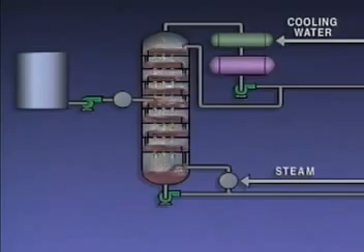Although all distillation towers serve the same basic function, they don't all have the same internal components. One type of tower uses trays called sieve trays to separate vapors and liquid. That type of tower is covered in the tower operation part of this program. In this part, we'll look inside two other types of distillation towers and see how their internal components differ. Let's start with a tower that uses trays with bubble caps.